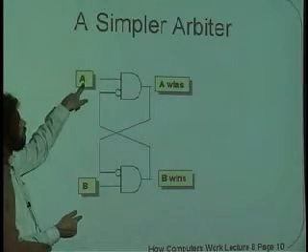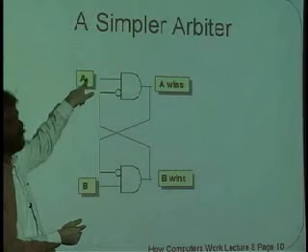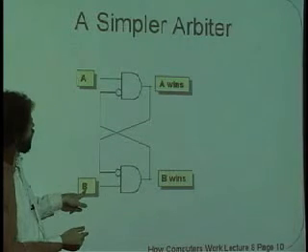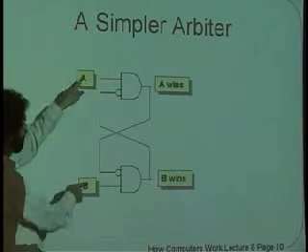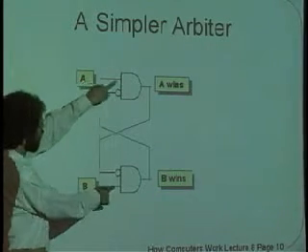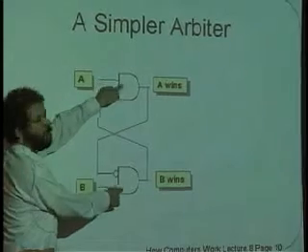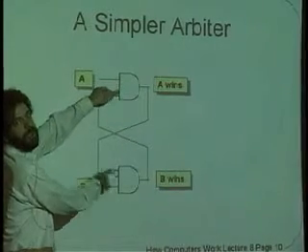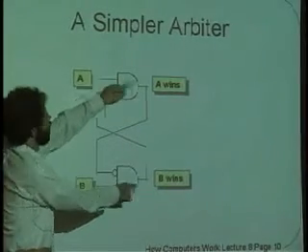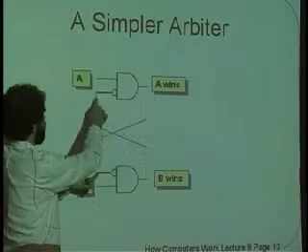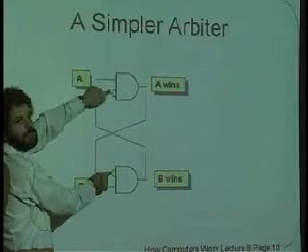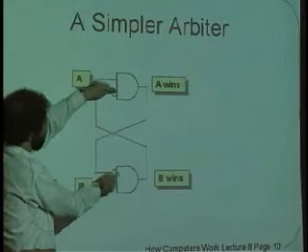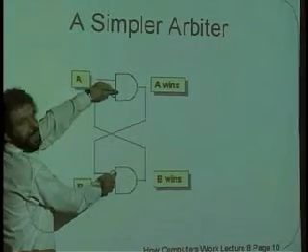If A presses a button and A goes from 0 to 1 before B goes from 0 to 1, then what takes place? Well, let's say both of them are low to begin with. If these are both low, what's the output of the AND of a low thing and anything else? Low. Okay, so these are both low, and they both cross around like this. Beautiful circuit with symmetry. And they go to an inversion, which is high. So both of these have high inputs right at the input to the AND here.